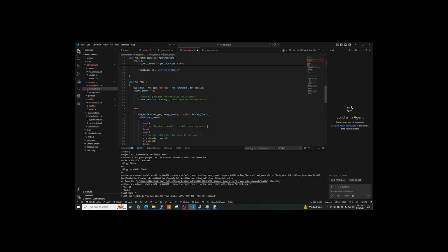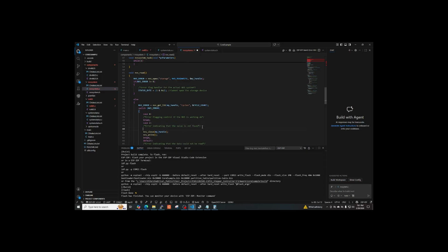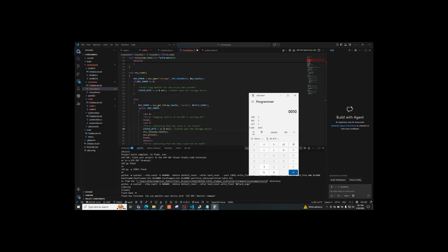Which error? Okay, status byte. So it'll flag this error the very first time the system boots up, but that's only for a new install. When I'm going to be building and selling these, I'll flash them and do the in-house testing, so this error won't exist on devices. So that's going to be at bit position 2. So hex 4.